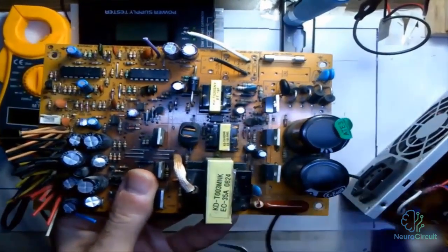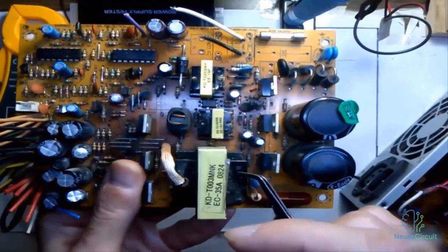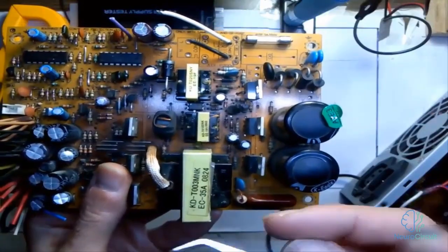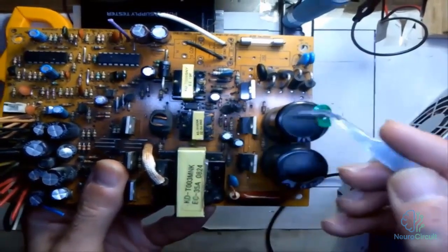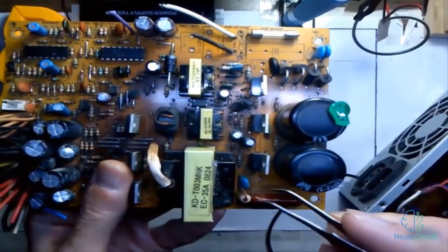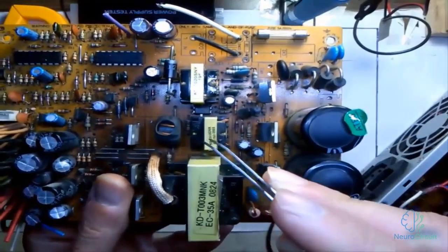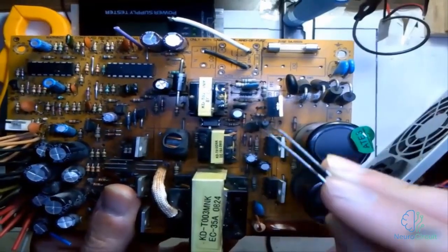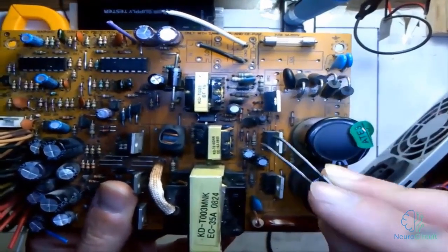In the next sessions, the DC electricity that enters the capacitors, after passing through the capacitor section, enters the transformers. But there's a problem here. Transformers can never operate on DC electricity. So how does this DC electricity actually enter the transformers? In fact, before this DC electricity enters the transformers, it is converted back to AC by a circuit placed here, which is also called the start circuit, and by the transistors you see here.